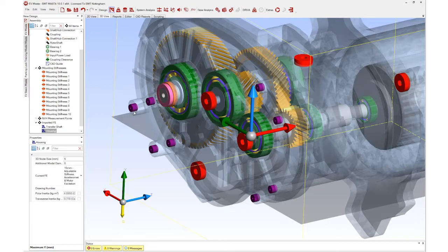One way is to actually make some condensation nodes manually on the casing at the places that you want the mounting points to be, and then positioning the rigid bonds at those particular points. Or alternatively, you can position the rigid bonds at the points beforehand and then just create the condensation nodes from that particular rigid bond. Each one has its own benefits. They don't really take more time than one another, and they're both relatively simple procedures. And because this is getting more common, we're looking at making this a little easier moving forward as well.